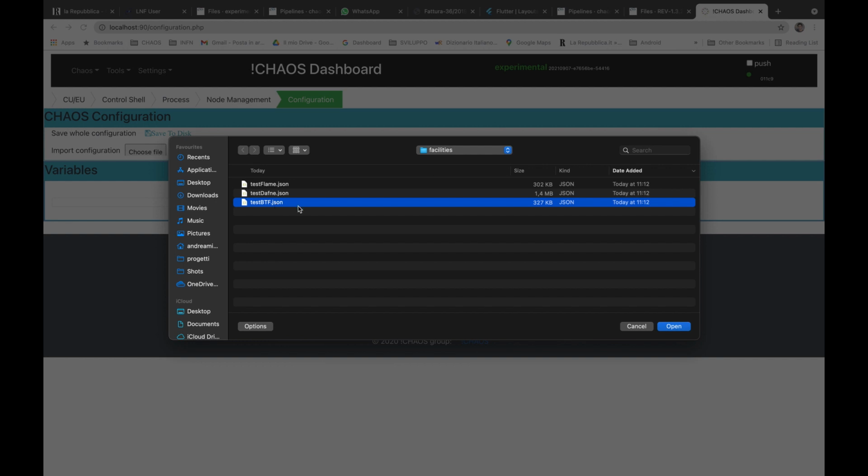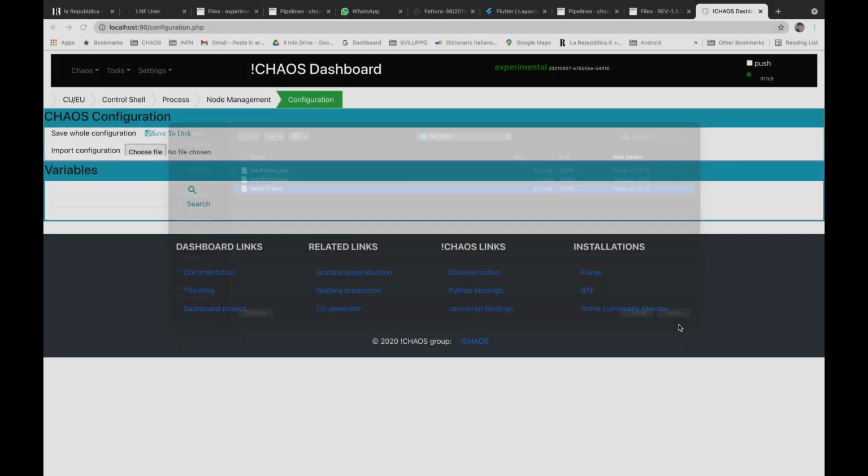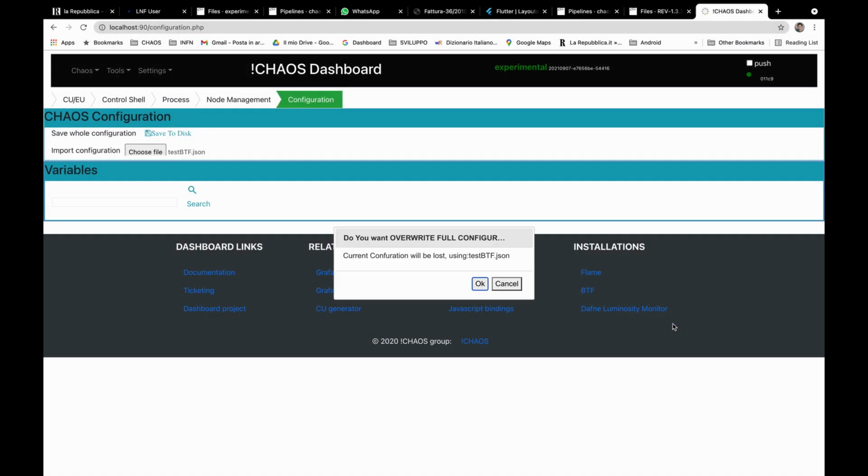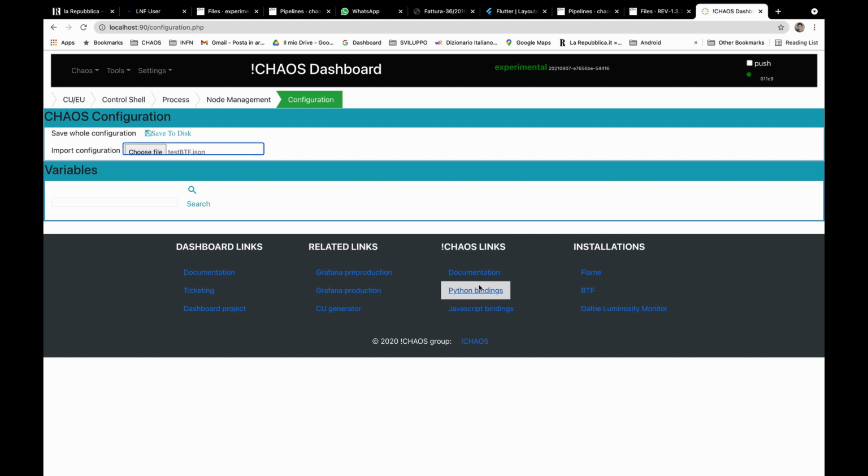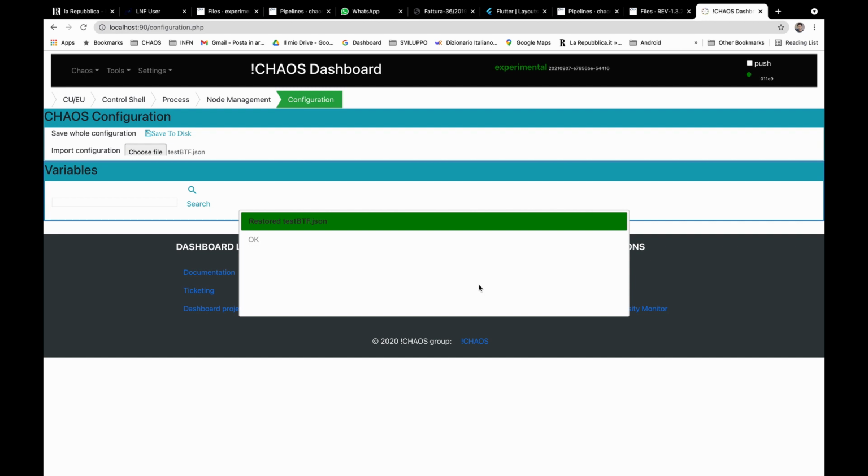At this point no unit server, control unit or execution unit is alive. The first time we should manually start the unit servers that contain the control units and the execution units we are interested in. All the services, control units and execution units can be configured to start automatically.